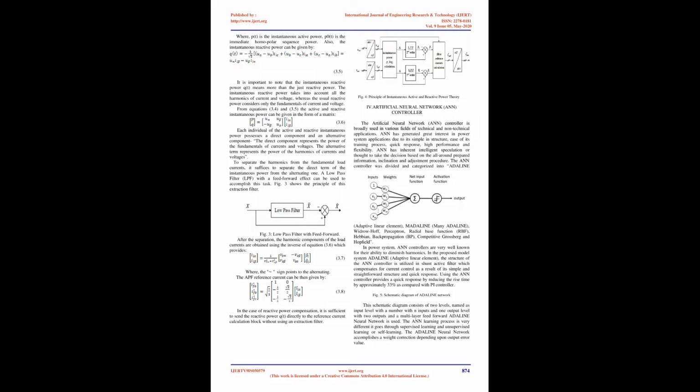The purpose of active power filtering is to mitigate the harmonic currents generated by nonlinear loads and to guarantee the retention of the sinusoidal form of currents and voltages. The primary step in active filtering is the extraction of the harmonic currents that are to be injected into the network. Good harmonic extraction is important for a good active power filter.